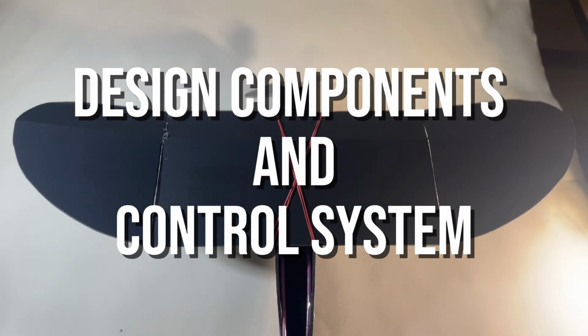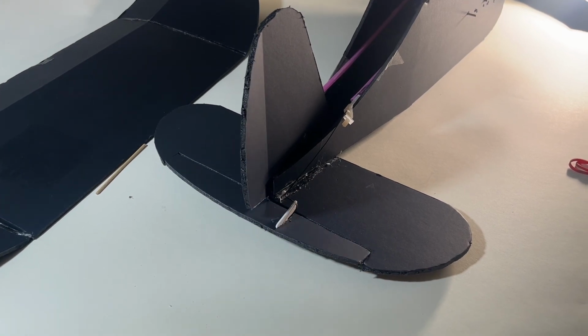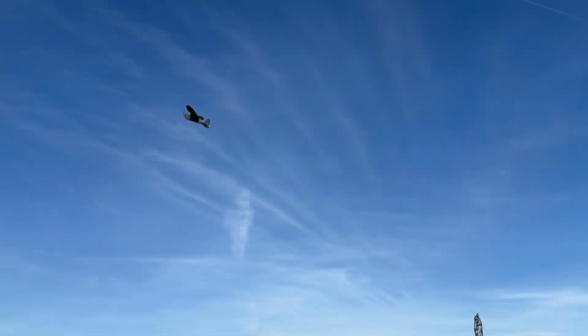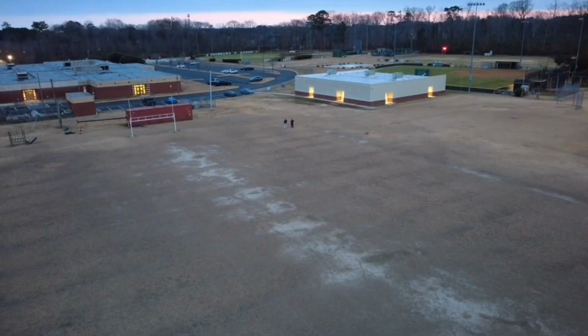For control, we kept it simple with just an elevator and rudder. The elevator controls pitch, so it sets the climb angle, helps maintain altitude, and also lets you recover smoothly if the nose starts dropping. The rudder controls yaw, which we use to start turns and correct heading.